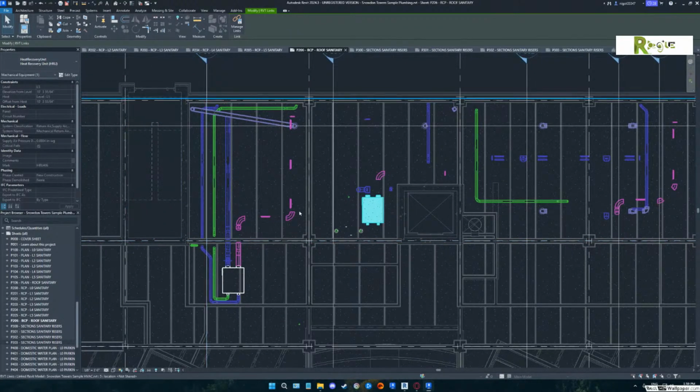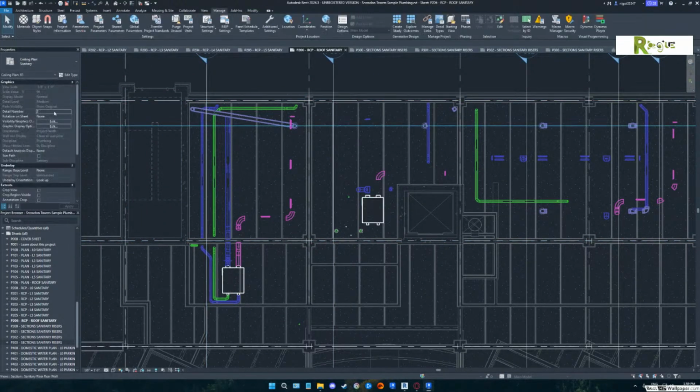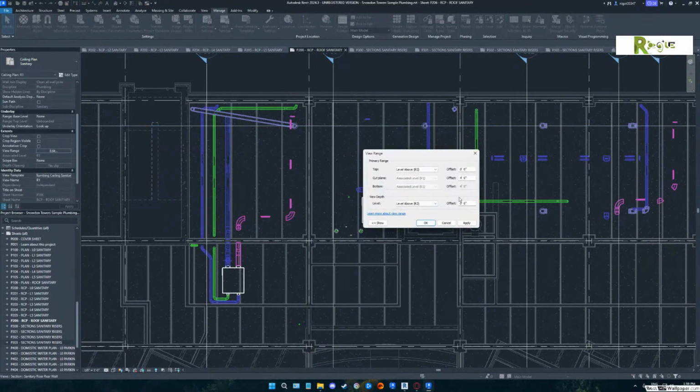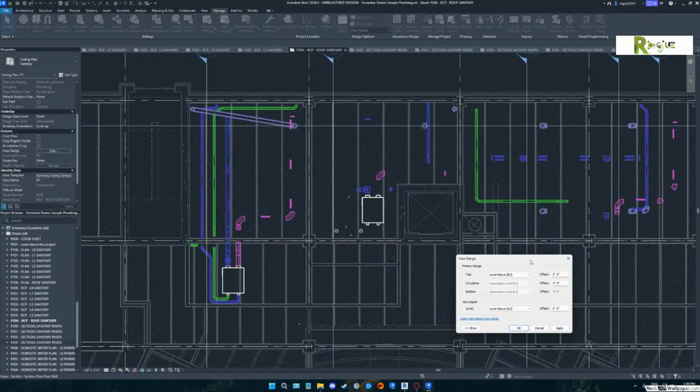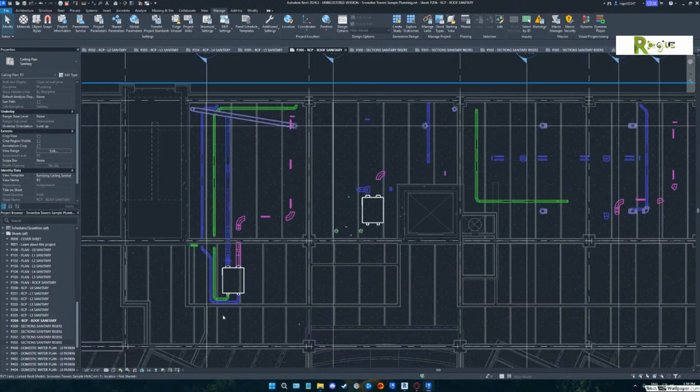But I don't understand why they don't have any roof. They drew the roof lines, the roof drainage, but don't use it. Is there one? There is one up there. Yeah, that would probably be. The cut plane is at 4, above 4 foot to the bottom. That bottom one's the one that's killing them, and that's actually applied by a view template. That's pretty funny.